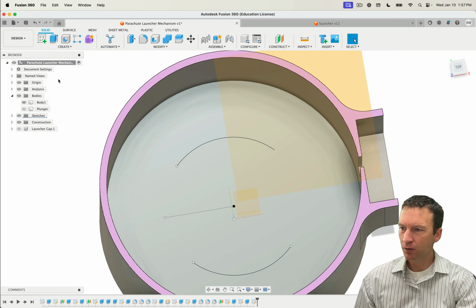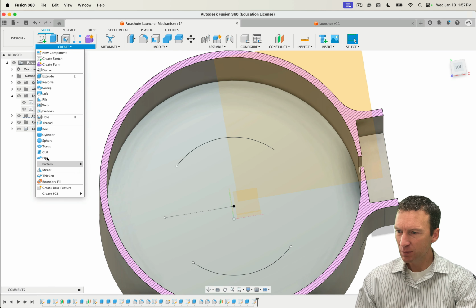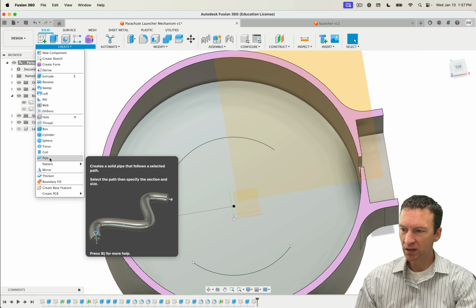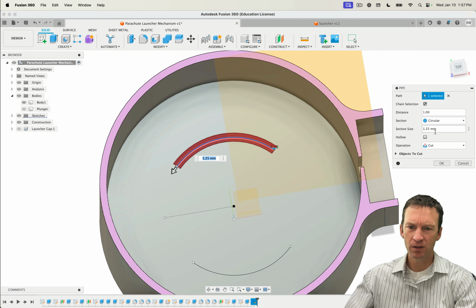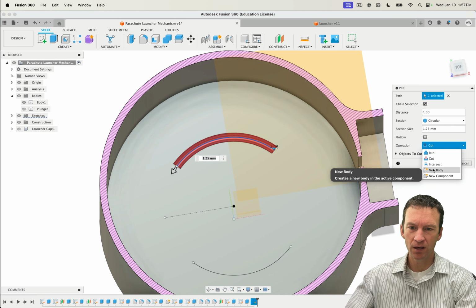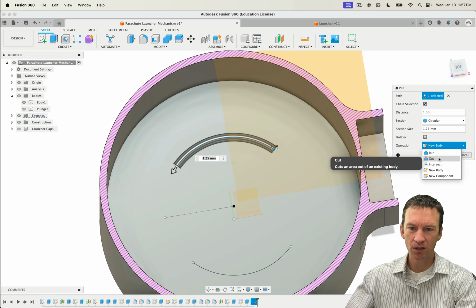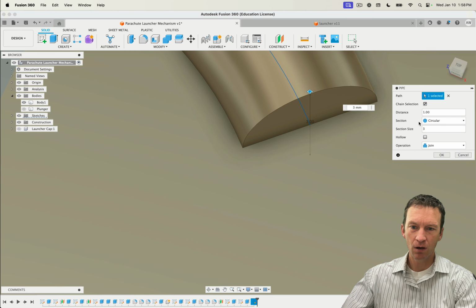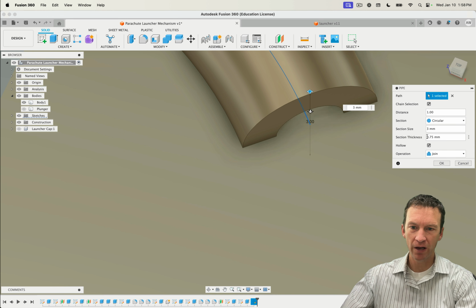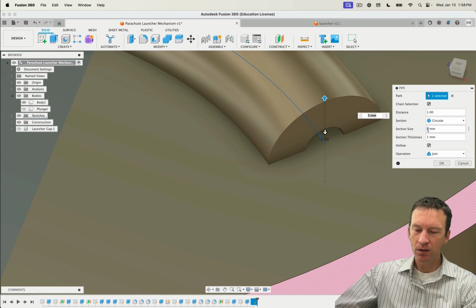And now I can create the pipes on those 2 pieces of geometry. So I can create one there, and I don't know, can we do these both at the same time? We're gonna go ahead and say a new body here. Actually, we're gonna say, whoops, not W, 3. And then you can also come in here and cut this. So instead of circular, there we go, hollow it out, and then we can have the thickness on the inside. Maybe we'll set this to 4.